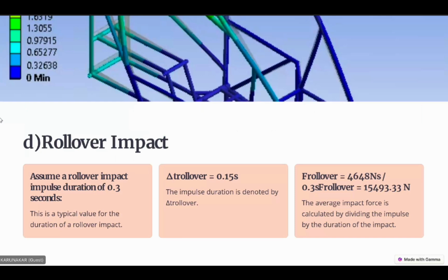And the common problems associated with AISI 4130: it is difficult to use with arc welding, where the metal properties can degrade. As gas tungsten arc welding concentrates more heat on a particular area, the cooling rate is highly unstable in the heat affected zone.